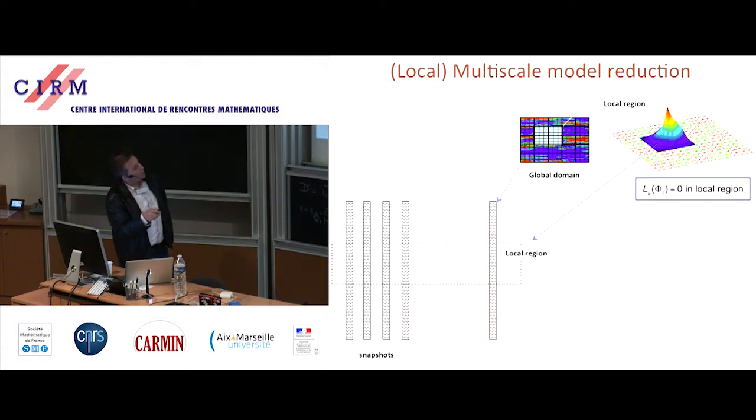That is, this basis function is described on its domain on the fine mesh. So any evaluation that we need to do of this basis function or its gradient or anything like that has to go through the coarse model into the local region by extension, and then we have to evaluate everything on each of the degrees of freedom, which tends to be fairly expensive anyway.